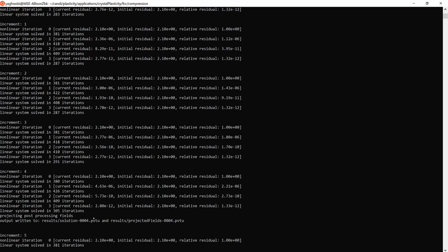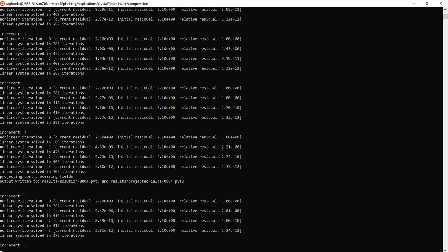So we will kill the simulation after the first set of post-processing files are out. You can see that in the first increments we don't have that output written, but here at the 5th increment, be careful, we start with number 0, at the 5th increment we are having them outputted. So we kill the simulation.